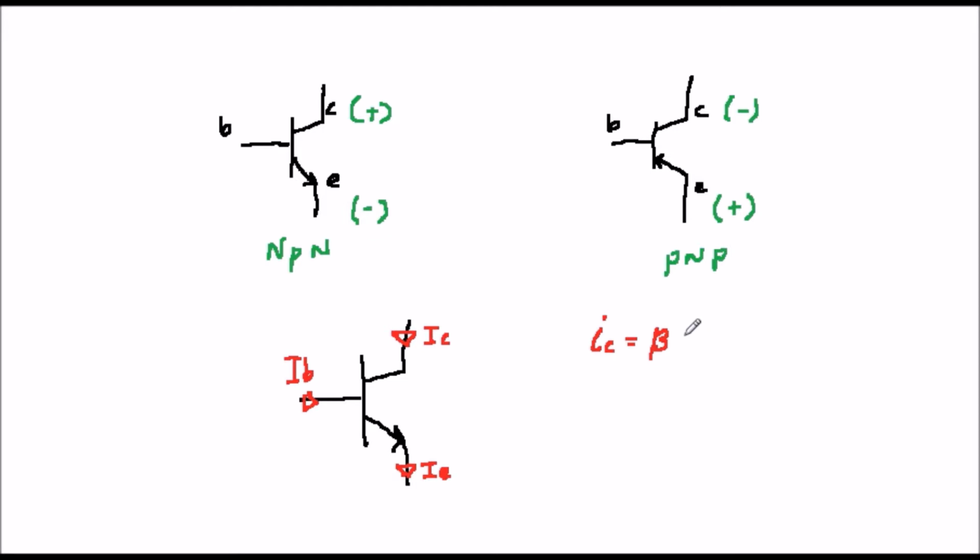Of course, as we discussed in video number 59, to act as an amplifier, the signal on the control line, that is the base, must be smaller than the current which it is controlling. In the case of this type of transistor, which incidentally is called a Bipolar Junction Transistor or BJT, the control signal is usually considered to be a current, although this is a first approximation and we'll discuss this in more detail later.